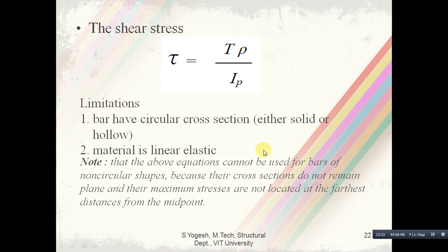And the main note is that the above equation cannot be used for bars of non-circular shape, because their cross sections do not remain plane and their maximum stresses are not located at the farthest distance from the midpoint.